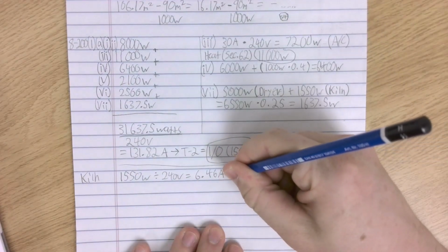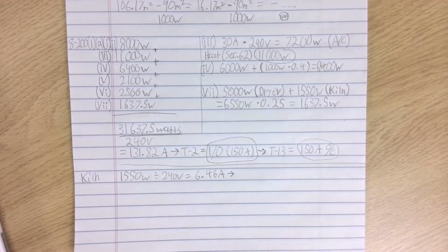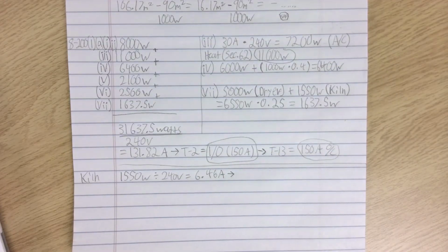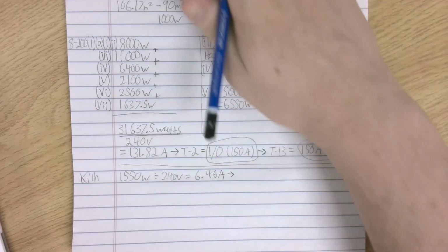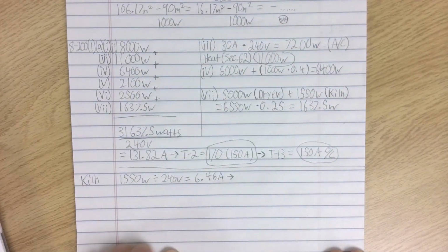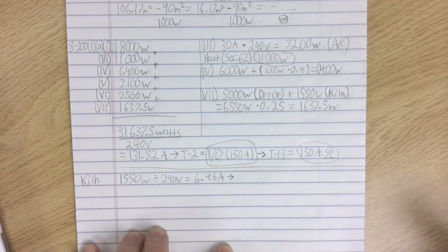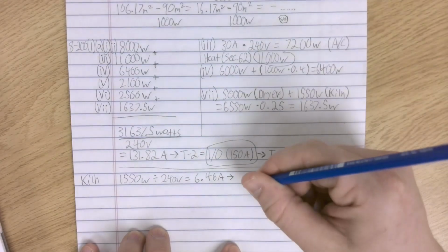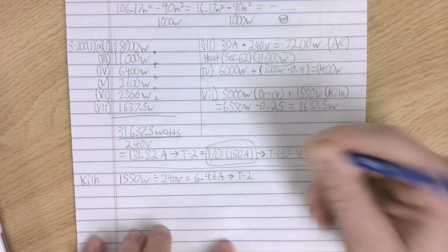So I'm probably going to run, it's in a house, so I'm most likely going to run some kind of cable through the house. I'm not going to be running it in conduit or anything crazy. It's 120, 240. So that means I'm probably going to run a 3-wire, and that's 3 wires in a cable. Cool. So I don't think I have to go to table 5 at all. Actually, I know I don't, because I did that section 4 module. And so I'm going to take that to table 2.